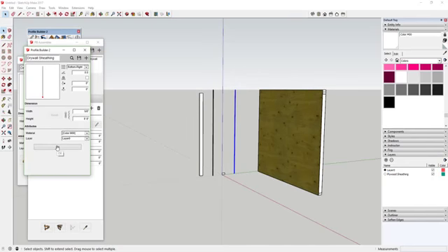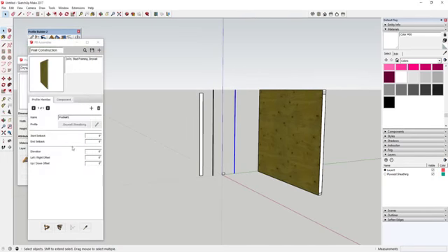It's like this. Go ahead and hit that OK button. You can call this drywall sheathing. And you're probably going to have to set your left-right offset for your drywall to 1.25 inches, just like this. So that'll get it outside of your plywood sheathing on this wall.